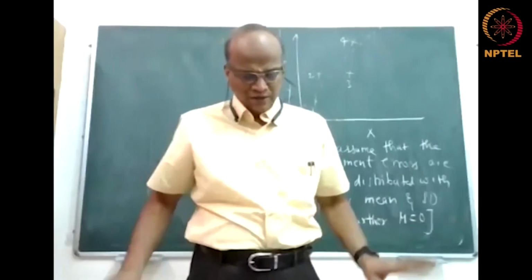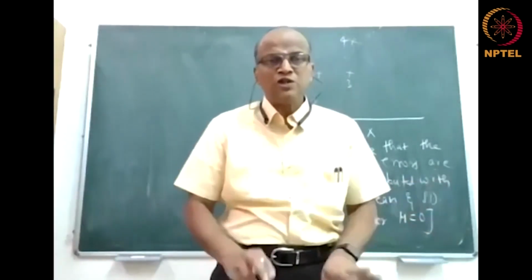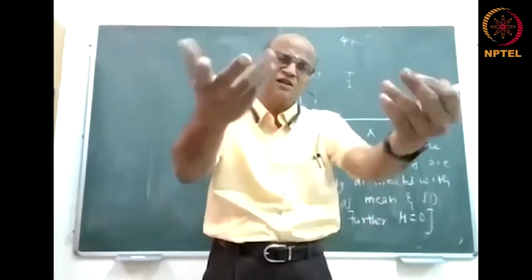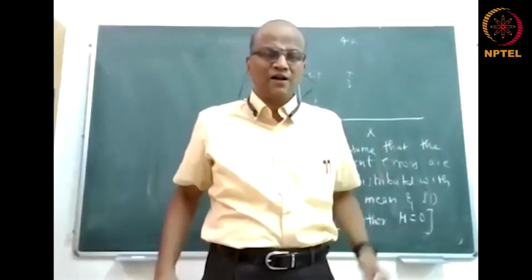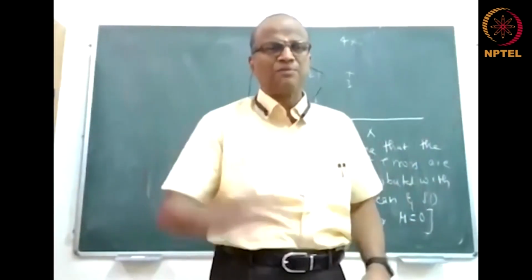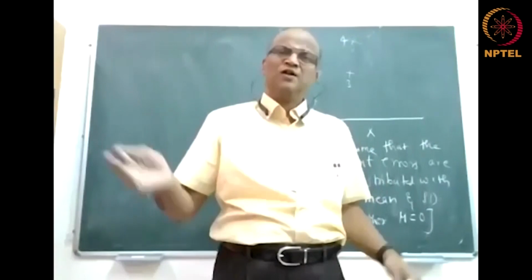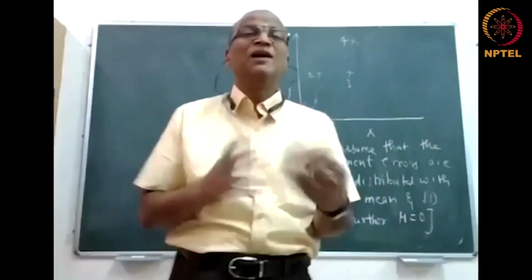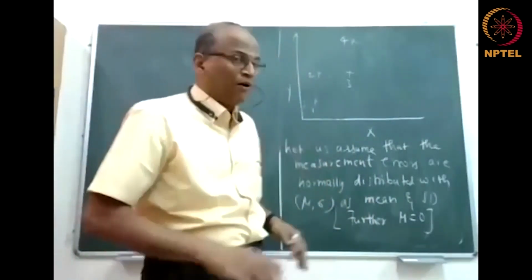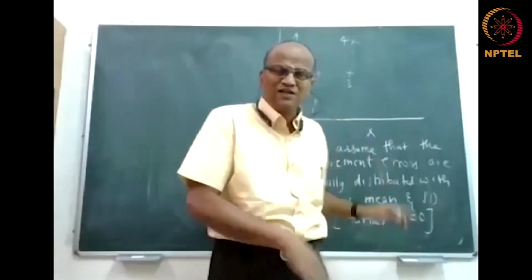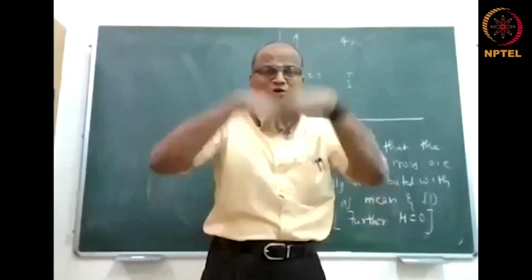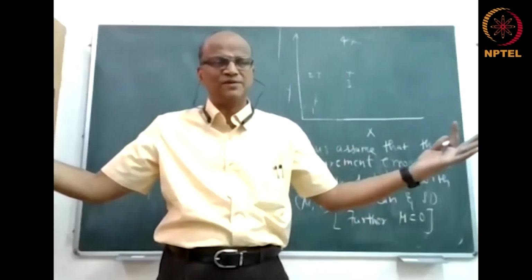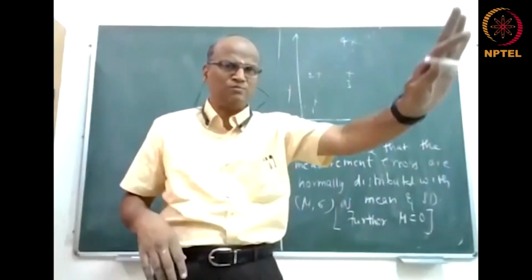That is, on a weighing machine, if you switch it on and it shows 1 kg, that is something you know. It is not a statistical error. Then whenever you measure something, you will always subtract that 1 kg. Even if the mean is not 0, that is called a zero error, and you can make a 0 correction. Around that default, even if it is 1, the errors are normally distributed. So you just correct your bias.